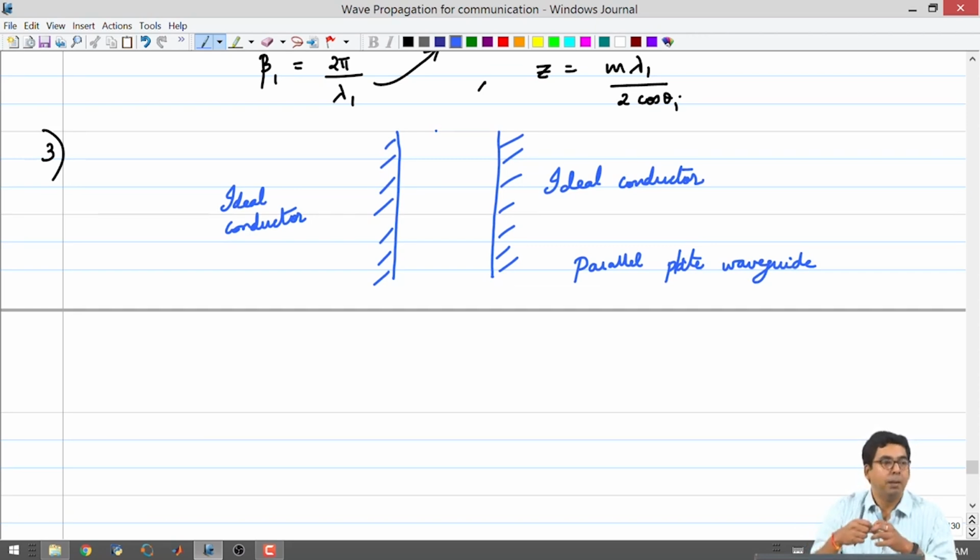Why one would use a delay element involves a lot of factors. For example, if you have two signals and you want to make a logical operation out of them, and, or, not, etc., you may get one signal on one of the input pins first, and you want to wait to make the decision after the second signal also arrives at the second pin, which means that you want to delay one signal with respect to the other, so that both of them arrive at the same time, etc.